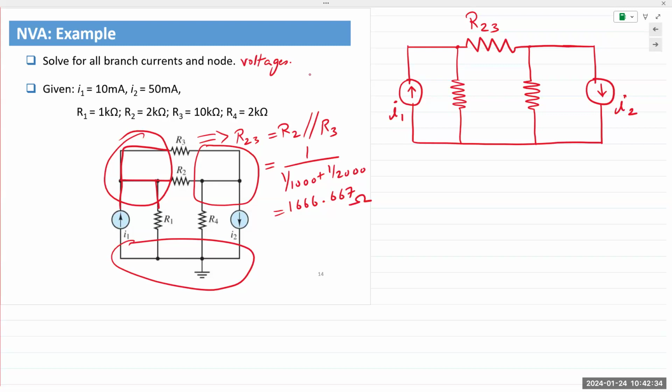Again, always keep in mind, a node is a junction, but the junction could be very, very short or very, very long. On a circuit schematic, it could be a tiny dot, a short line, or a very long line, but it is still a connection. It is still the exact same node. Take an example of a power extension cable: take this orange power extension cable, 100 feet long, and plug it into a wall outlet. You would expect to get zapped if you stick your finger at the other end, right? It's the exact same node.